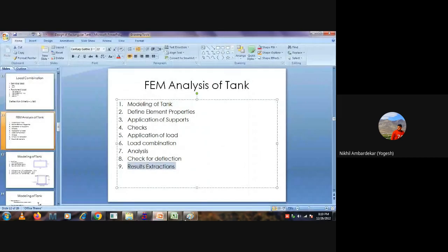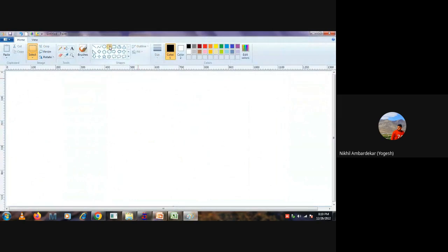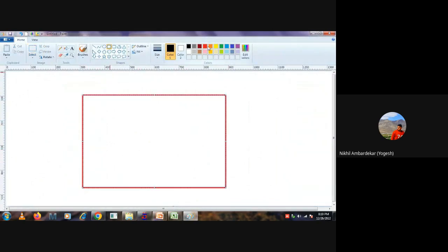So if I go to this, suppose this is your slab, so if you provide an opening like this, then in the FEM model it can be fine based on the size and span. Sometimes a plain slab can be possible, but if your span is large, then what you need to do? Because what happened? You are breaking this span, correct? Because this edge, this edge, this edge, and this edge are not supported, correct? For a small tank opening or small span, it can be fine.